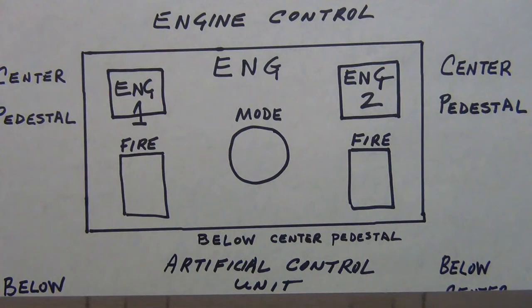And then just a little added thing with automatic engine start versus manual engine start. I'm going to say it again, but I remember I told you which shutoff valves on the fuel side open or not open. On manual engine start, the ignition is initiated using both igniters. Okay, that's just a noted aspect of manual engine start. On automatic engine start, you have an indication on the ECAM, on your engine warning display, in particular, of the N2.